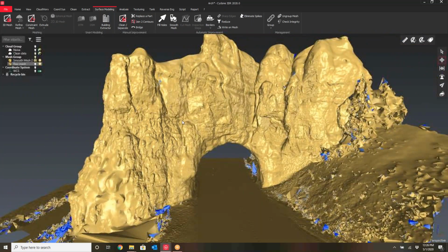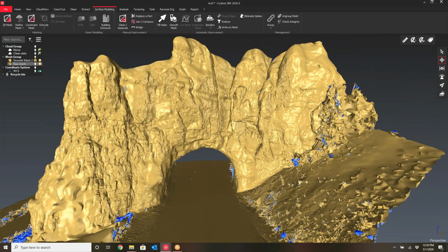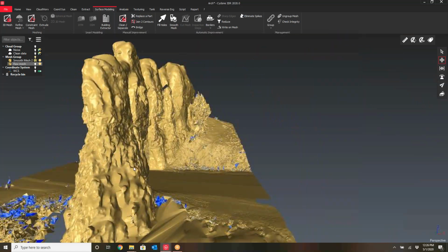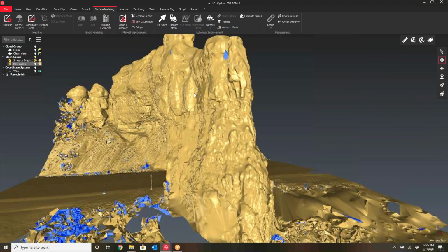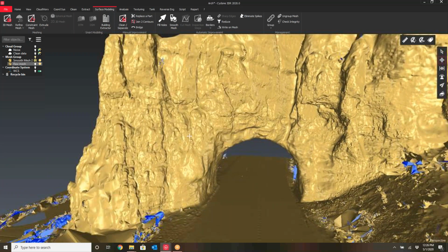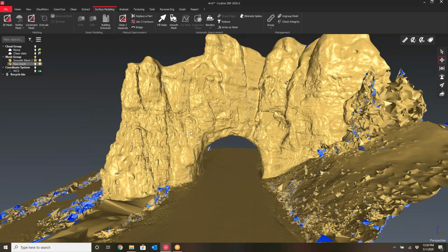So this once again goes out as an XML into Civil 3D or a DXF. We actually took this one as a DXF and put it into a robotic total station, and we were able to go out and do monitoring from the surface within one of the Leica robots. And so that was an awesome use of the system to check to see if the rain and erosion was happening, because they wanted to make sure that this road was safe to still use. Essentially, that's exactly what we did.